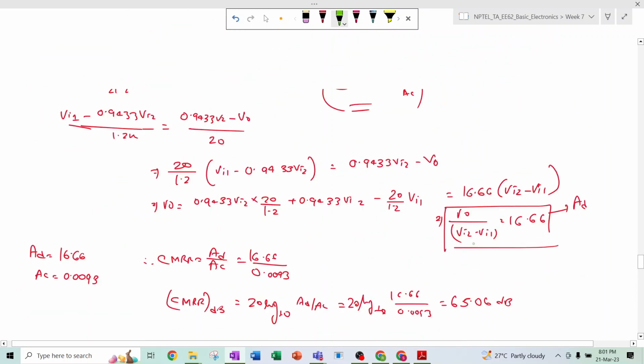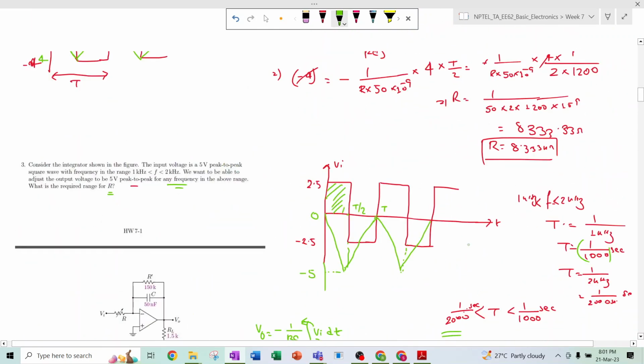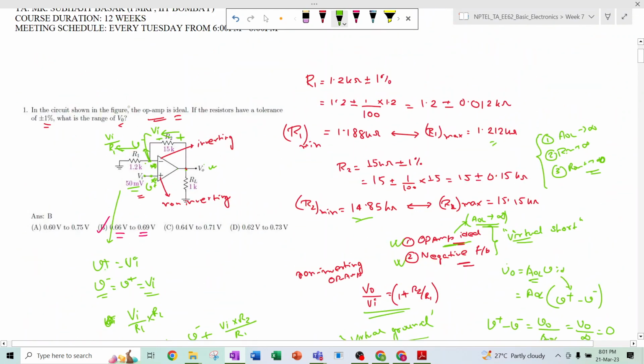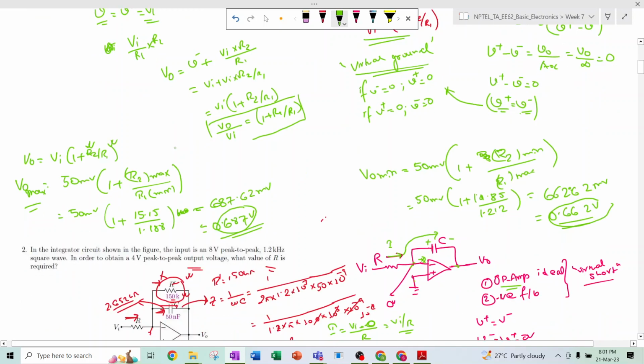Okay, so this is for today's session. I have completed all the things. Initially I did the op amp for the ideal cases, what it should be. If the op amp is ideal and the resistor has some variance, like how much it can tolerate, or if there are some resistance differences, then how the output voltage is going to differ from its original value.